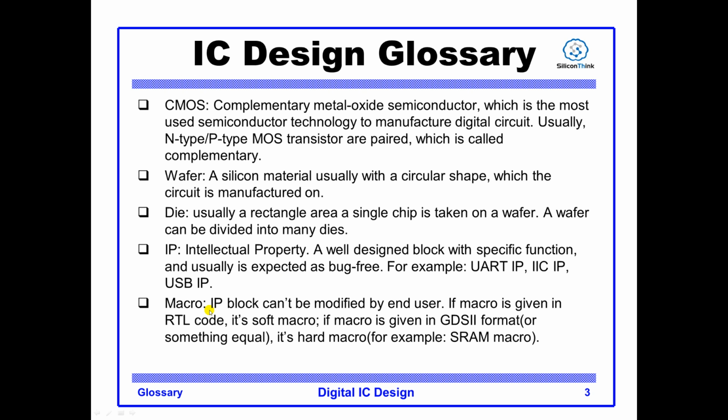Macro. A macro is a kind of IP block that can't be modified by the end user. If a macro is given as actual code, it's called a soft macro. If a macro is given in GDS2 format, it's a hard macro.